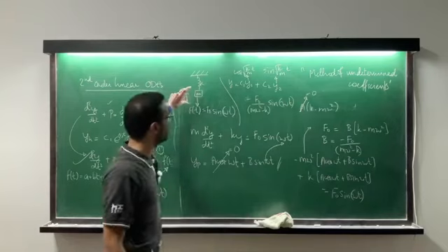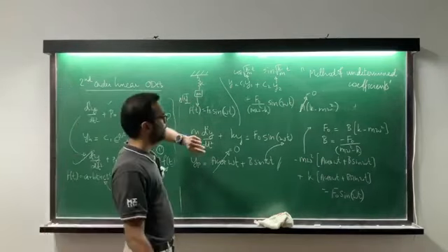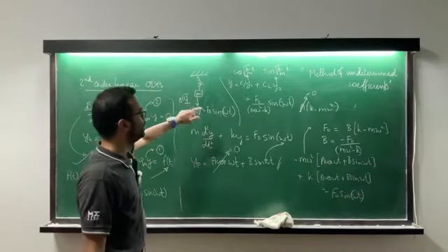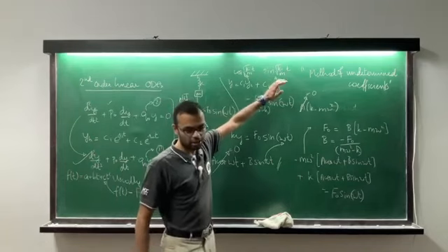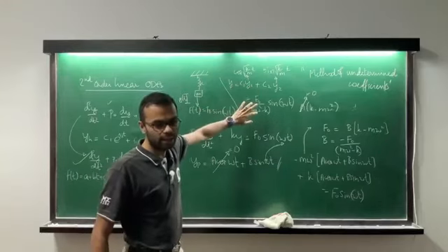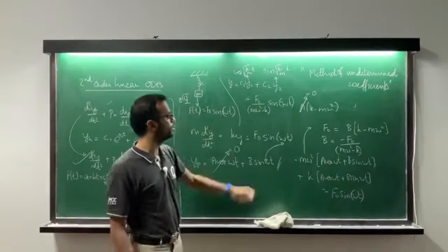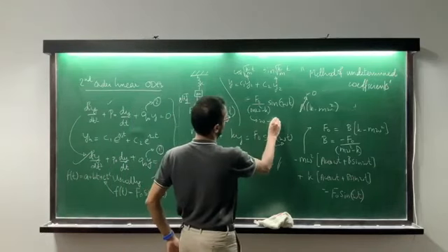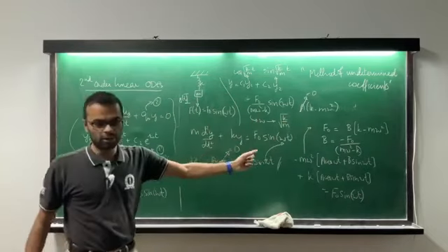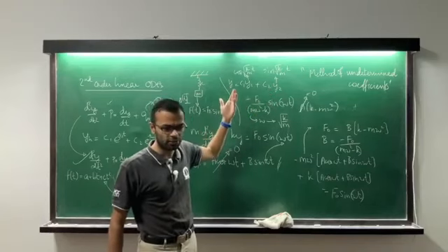Okay, so this is the amplitude of oscillation that the mass will undergo as it's forced by this type of term. And you can ask, when is the oscillation? These are transients, but in this case they are not transient because they don't die out. There is no damping, so they will also continue to oscillate. And in addition, you will have the superimposed oscillation. So the moment the forcing frequency omega goes closer to square root of k by m, this denominator becomes smaller and smaller, but these two coefficients don't. These two coefficients depend on the initial conditions, which are fixed.